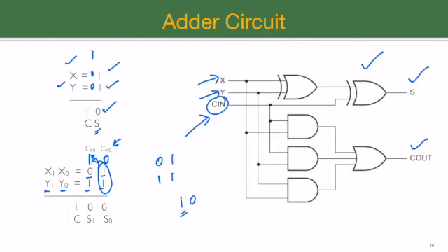Whenever you are performing 2-bit addition, there is a possibility that there was another addition operation before that, and a carry may have been produced from that point, which needs to come up and be added. So the carry is added, and 1 and 1 produces the result of 0 with a carry of 1.